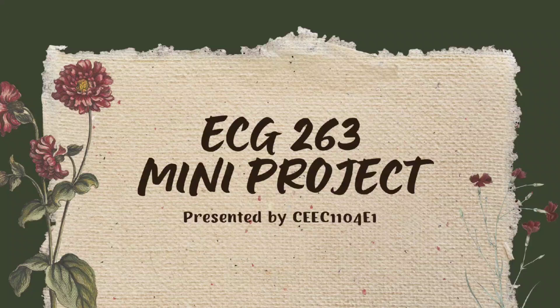In the grain size distribution analysis, we determined that the soil consisted of 82.33% of gravel, 17.48% of sand, and 0.19% of silt. The soil is classified as silty sand. This classification is important as it gives us an idea of the soil's drainage properties and its behavior under load. Silty sand typically has good drainage but can be susceptible to erosion if not properly managed.